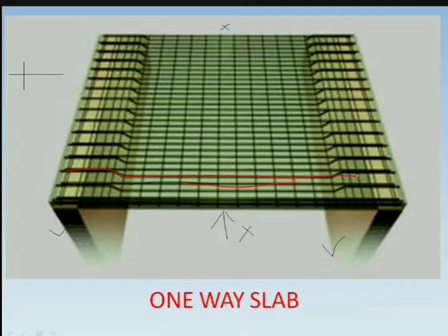Okay, it goes straight. Then the other bar will be there, which is bent this side, comes, it goes straight. This is alternate bending. One after another, you will have the bending done, which is a one-way slab. Okay, so these bending, I'll be telling you all once again when we solve an example.